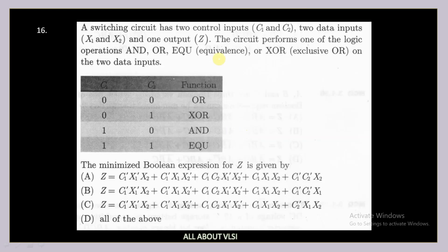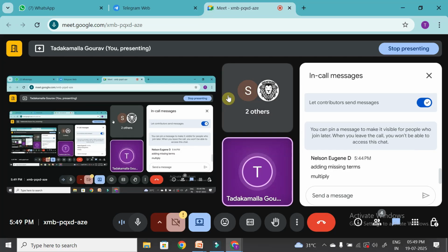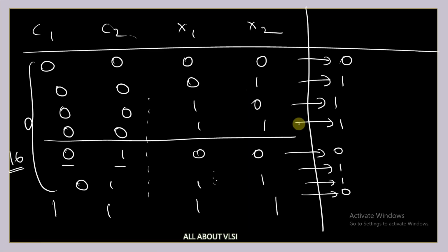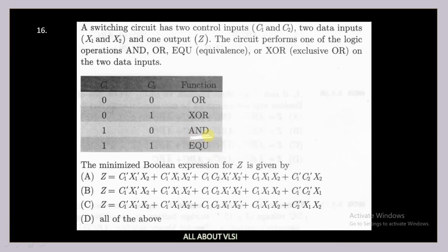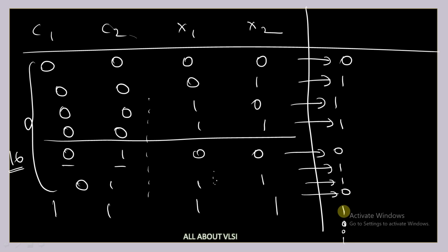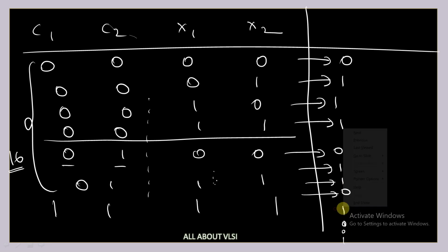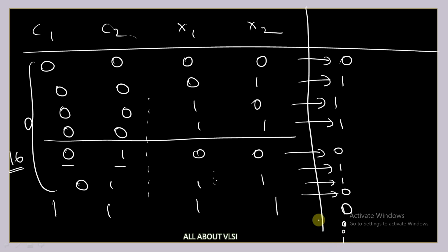And next, you are going to find the equivalence. For equivalence, what operation are we going to do, XOR or XNOR? For finding equivalence, that is, when both inputs are equal, we perform the XNOR operation. Exactly. So here the next set of outputs is 1 0 0 1. Next we have the AND gate, so the output is 0 0 0 1, followed by 1 0 0 1.